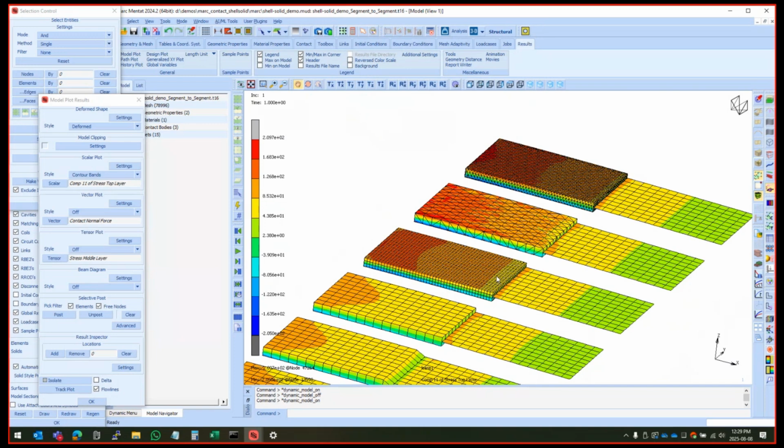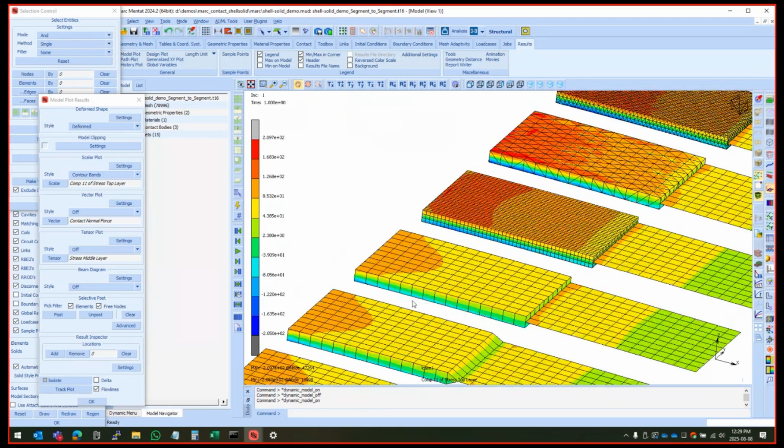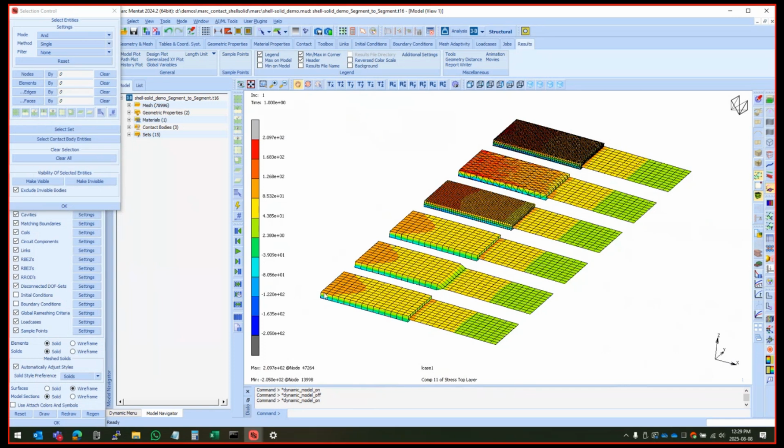Just the mesh in the third and the fourth models, the stress on them look different. The third and the fourth models. So that one and that one. Yes. Obviously this is 4 through the thickness, that's 1 through the thickness. So it's one of the big issues we have with this kind of a model. We expect to see a constant stress in that direction, right? So the stress in the X direction, but we expect to see the same stress there and there. Do you agree? The reason we don't is because of Poisson's ratio.